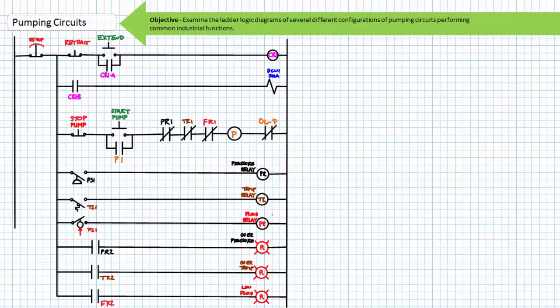It may seem that this implementation uses more hardware than that of the mechanically interlocked switch pairs. However, realize hardwire relay-based ladder logic is being replaced with programmable logic controllers, PLCs, that can utilize programmed virtual elements to serve the purpose of physical relays. This implementation utilizing relays might be better suited for a PLC, since it would actually use less hardware, wiring, and 3 non-mechanically interlocked switches. We'll discuss PLCs and PLC programming in later lectures.